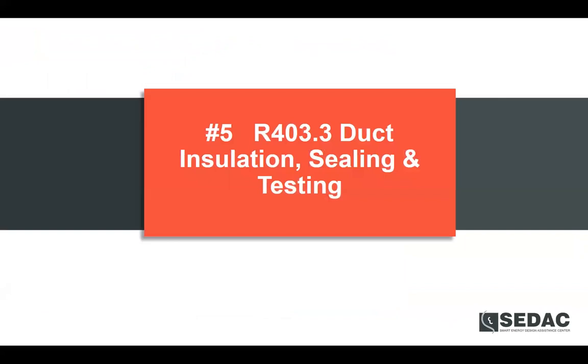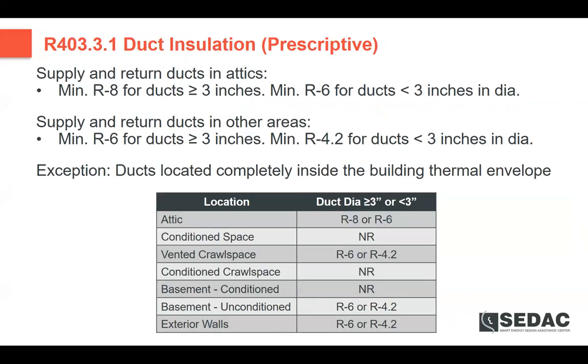As far as duct insulation and sealing, this is again a prescriptive requirement, noting that if ducts are leaving conditioned space, we need to make sure that we are insulating our ducts. Because frequently we see air handlers up in attics or down in crawl spaces. It's kind of hard to make ice cream while you're sitting in your attic. So we want to make sure that we're insulating this, not only from an energy standpoint, but also from a moisture and mold potential standpoint.